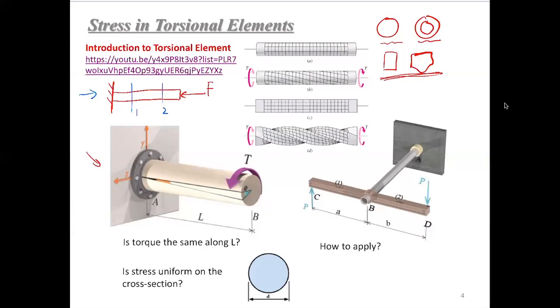Internal forces? Why? Okay, we determine internal forces using a free body diagram, right? So if we're looking at position 2, we cut it at position 2, make it free, and add the internal force here, let's call it F2. After the free body diagram, we will have an equilibrium equation. What is the equilibrium equation? That will be negative F2 minus F equals 0, right?